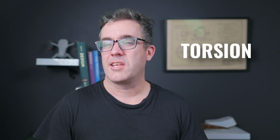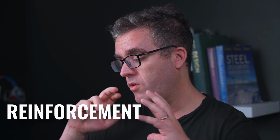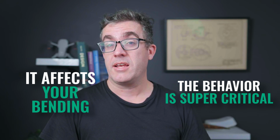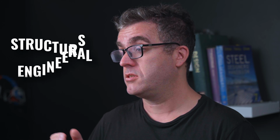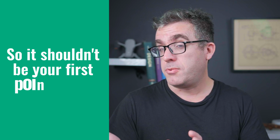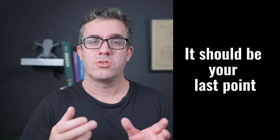Torsion is one of those things that every engineer hates. As the reinforcement is high, the behavior is super critical as it affects your bending so much. So it's something that us as structural engineers try and avoid through good detailing. So it shouldn't be your first point of call, it should be your last point to try and achieve the architectural freedom.